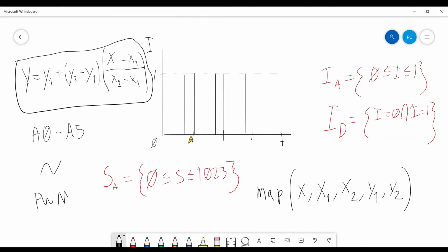So let's say that right here, that's 0.8 in relation to the increment, which means that the signal is on for only 80% of the time. This is called a duty cycle. D-U-T-Y C-Y-C-L-E. Duty cycle. Now, the duty cycle is basically how much percent of the increment that it's on.